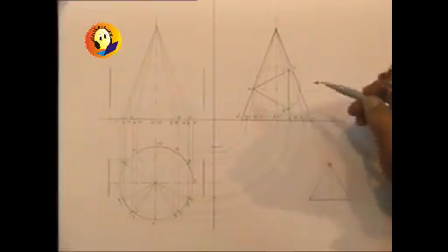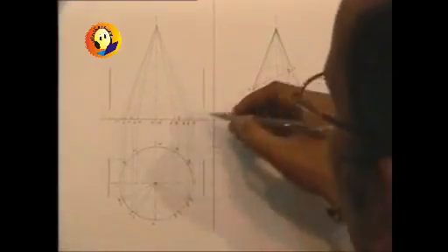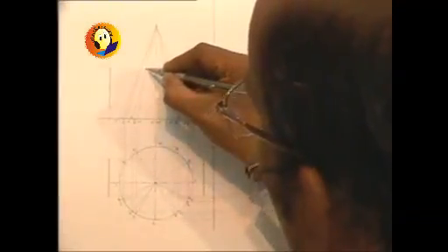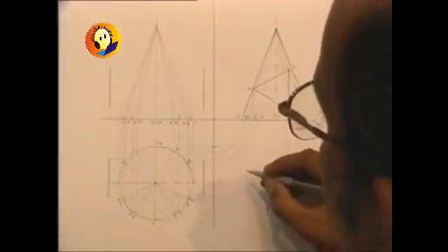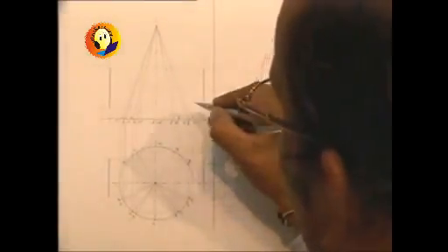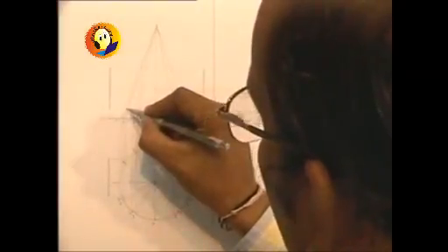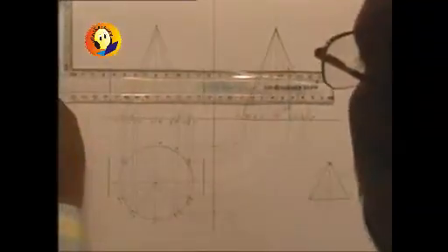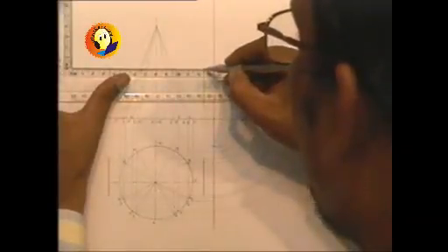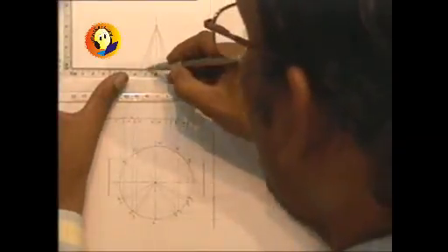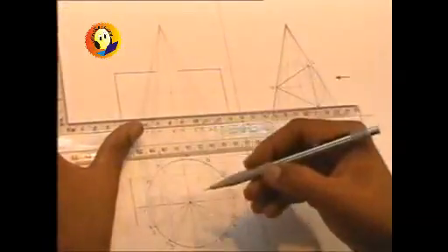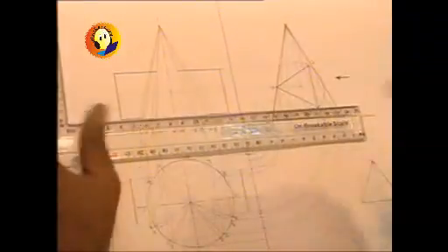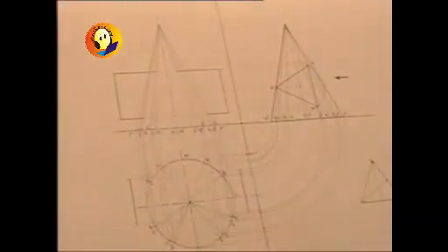face BC. So point C can be marked directly on generator C dash. Point C can be marked on generator C dash, and point B can be marked on generator B dash, which is not a very complicated thing as such. So these are the 2 points at which the vertical face is entering inside the cone. So you can darken that much part. So these points are marked in the front view.